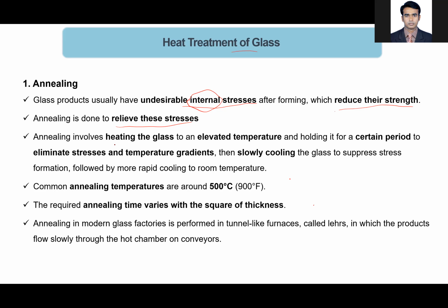That means you have to heat the glass to an elevated temperature, not the melting point temperature, at some recrystallization temperature where glass molecules can reorganize themselves, and hold it there for a certain period to allow the glass molecules to move around and fix their spaces and become stable, and that will cause the elimination of internal stress and the temperature gradient.